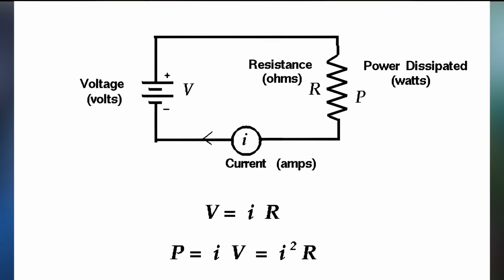And so if I have this wire connecting my 2 terminals directly without any other what we call load on the circuit, so I don't have any light bulb or anything else in there, then I draw a very high current, I deplete the battery very rapidly, the wire heats up, potentially causes a fire, and we get what's called a short circuit. So this is a short circuit, when you connect up the 2 terminals of the battery or 2 ends of a circuit without any load to dissipate the energy in between them. It's a big fire risk, short circuits, because the wire can heat up so much that it can cause fires. So that's one reason why it's important to insulate electrical devices, is to try and prevent short circuits, which can cause fires and damage the electric components as well.